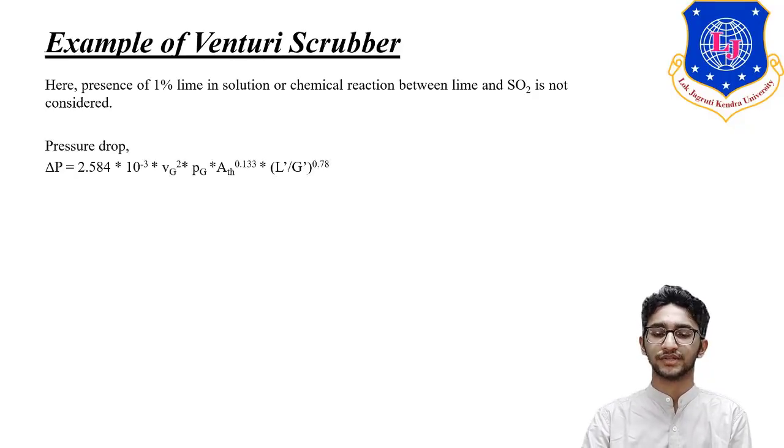Now the pressure drop required in the Venturi scrubber is obtained from this equation, that is 2.584 multiplied by 10 to the power minus 3 Vg square rho g into ATH raised to 0.133 into (L dash upon G dash) raised to 0.78. Vg is given as 100 meter per second. ATH is pi by 4 di square. The di we have calculated earlier, so it is 886.7 centimeter square.